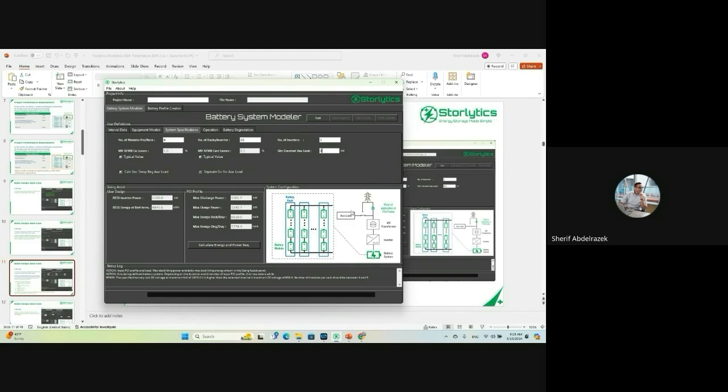So it really depends on your case. I know with Duke Energy, for most projects, you're sourcing aux load from the POI; you don't have a separate service. But for a lot of other utilities and companies, they assume they're getting a separate service for aux load. So you can do it a lot of different ways, and this feature allows you to account for that.